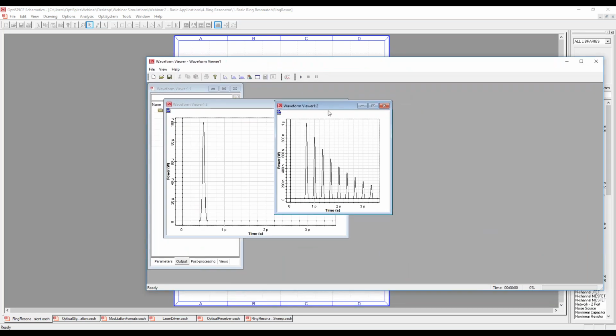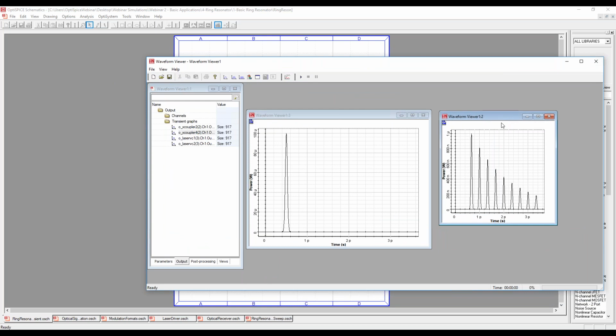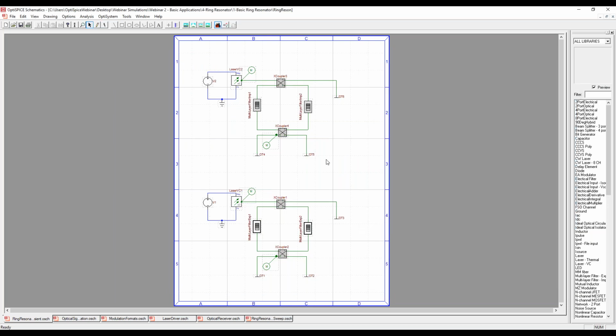So this is the most important difference between the explicit and the implicit multi-layer filter. In the explicit one, we are modeling every layer separately and explicitly, whereas in the implicit multi-layer filter, we're just taking all the layers and calculating transmission and reflection coefficients and simulating it that way, so we can't have certain filtering effects and we can't simulate the delay. Doing it using the implicit multi-layer filter helps you speed up your simulation, but then you lose some of the effects you can normally simulate.